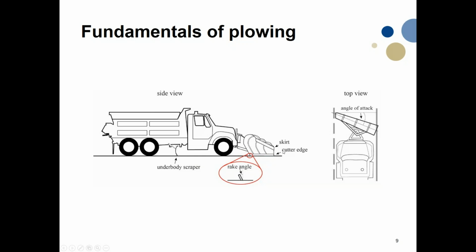That means that it doesn't really wear so hard, and the plow doesn't really flow. There is some contact pressure, but it's not so much. That's different for an underbody scraper. Here you can put much more force on your blade. You typically use another type of cutter edge, and this is intended to remove more compacted snow and is much more efficient to restore evenness in your compacted snow layer, while the plow is mainly made for removing the looser material.